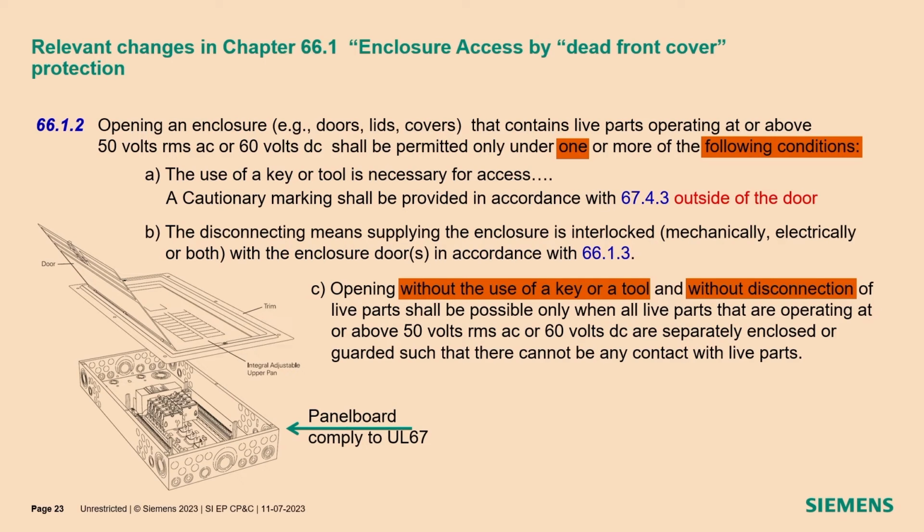You find there are a lot of solutions with panel boards in your house maybe. You have a house maybe and the light goes off. Then a kid can go down and switch it on, because it's pretty safe also for an unqualified person. These panel boards have nothing to do with industrial control panels. They have their own product standard, safety standard UL 67.